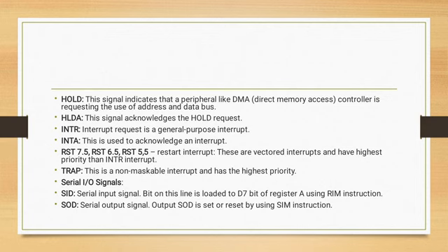And SOD, which is the output pin of the processor, is used for serial output, and the 7th bit of the accumulator is output on SOD when the SIM instruction is executed. Thank you.